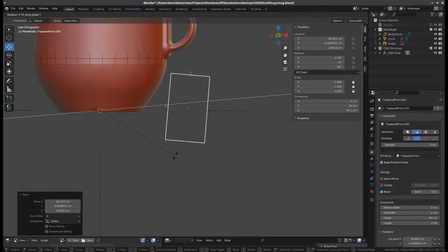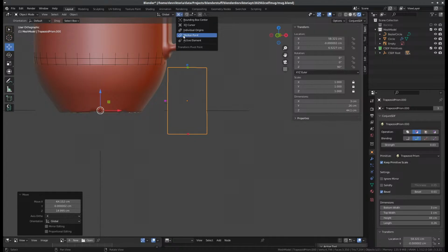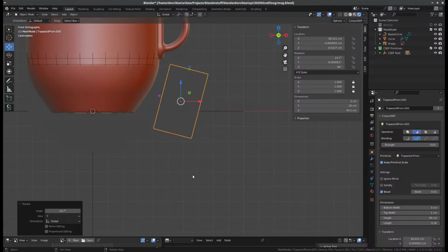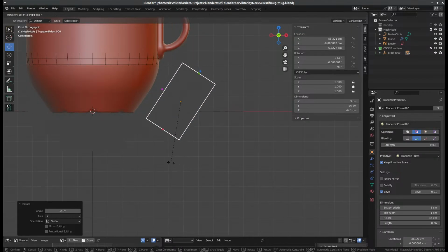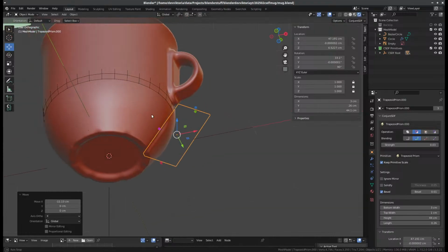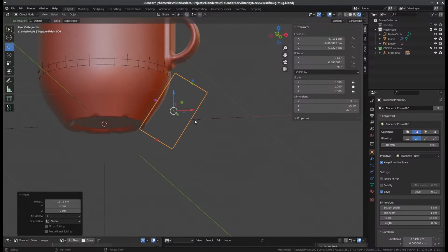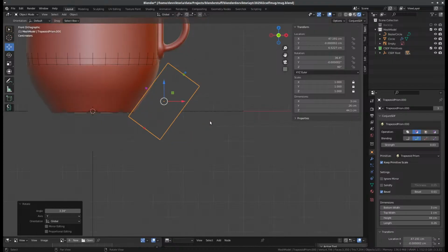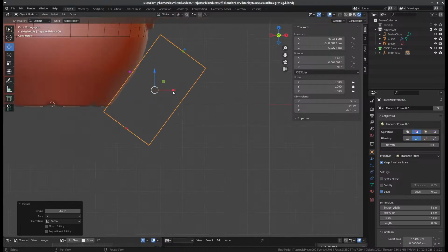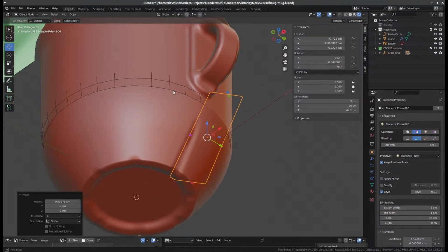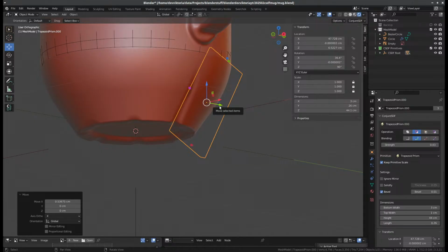And let's rotate it, and not via the 3D cursor, but around the median point. Let's rotate it around the y-axis, or Y a bit more. And let's just put it like so, RY, I think, and maybe a bit less. Yeah, this looks nice, I think.